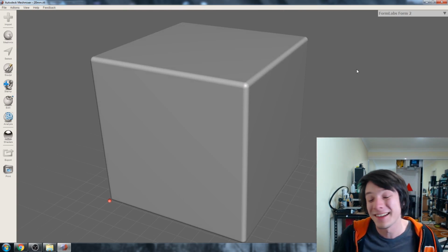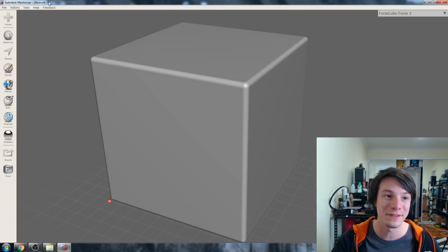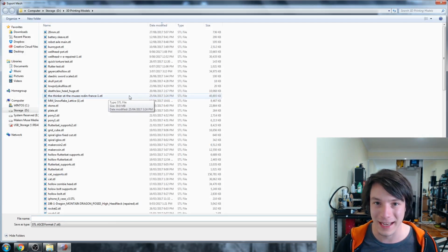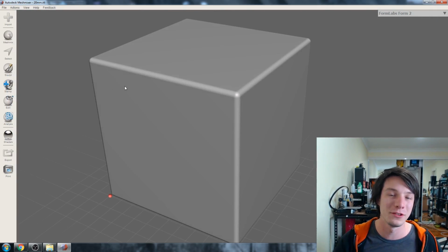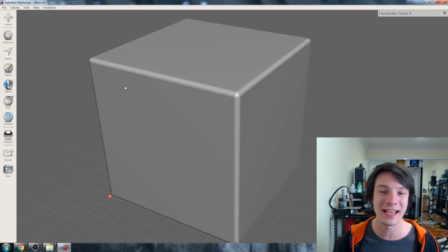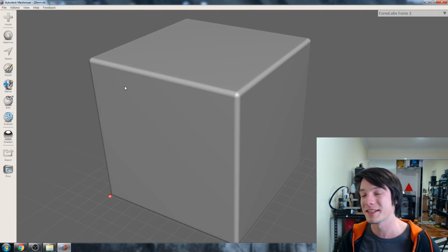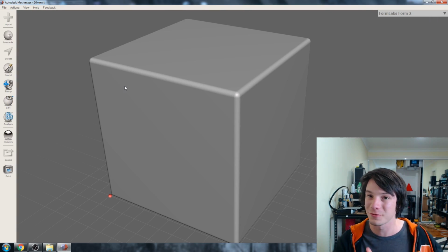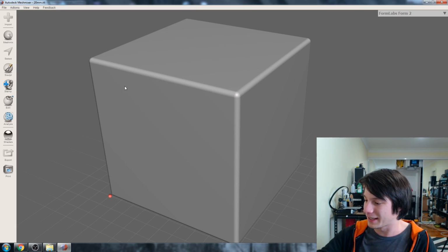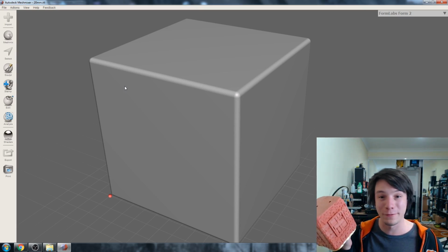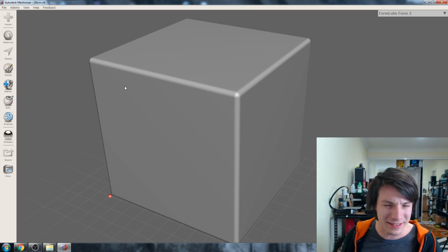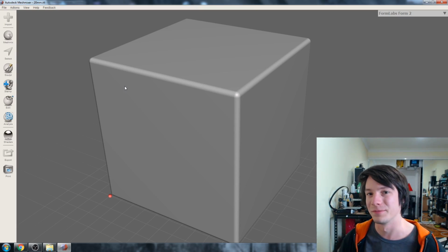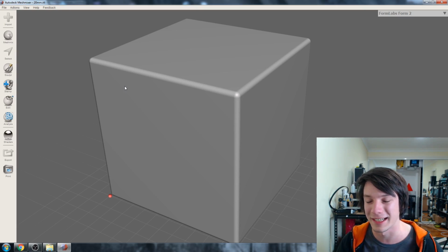But there's a really big downside to doing this. If I was to resave this as an STL file, it's going to lose that text. It's just going to resave the triangles as they are, and you will lose that text. Also, the other downside is saving as an ASCII versus a binary STL means the size is huge. So if you're trying to watermark this way, a complicated model like this, for example, STL files can be several, 90 megabytes in size. That's a lot of text that you're going to have to load up in your editor to dump your watermark into the actual code.